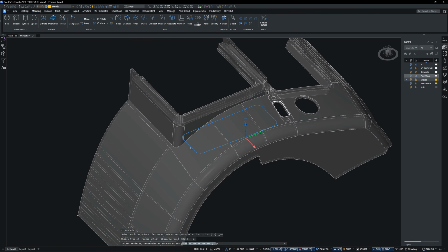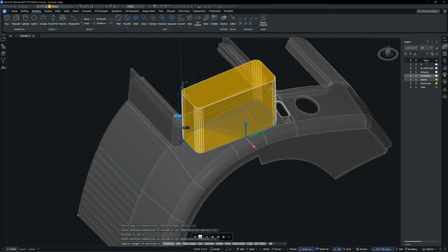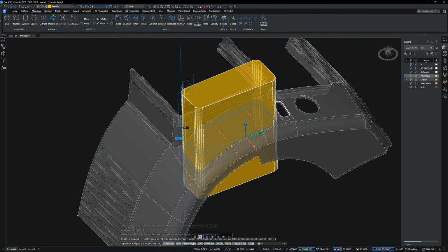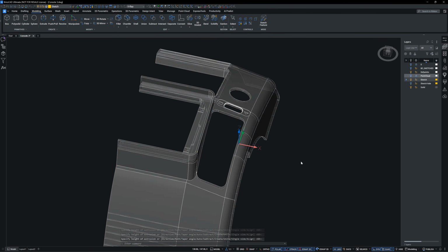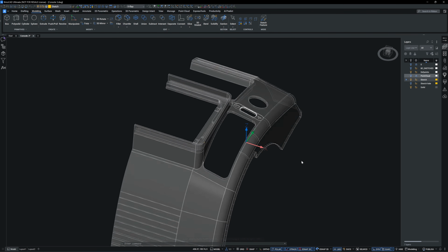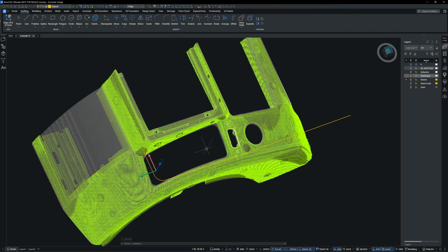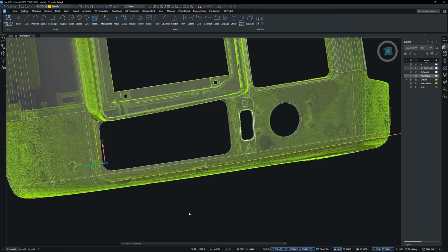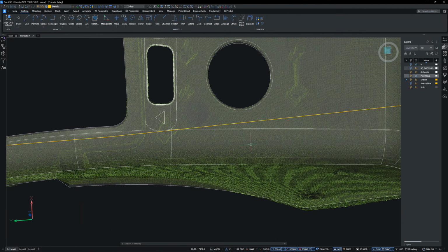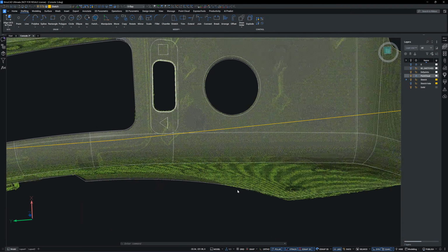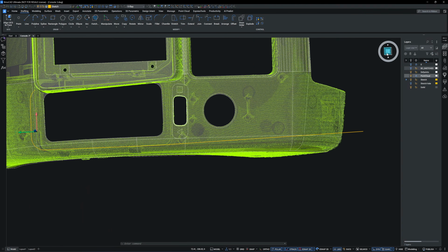Next, I create the fan grill cutout. Since the cutting angle aligns with the XY plane, I simply move the UCS onto it and perform an extrude cut. Next, I create the cosmetic emboss, a strip with a groove about 1 mm deep. I sweep a circular profile along the curved part.